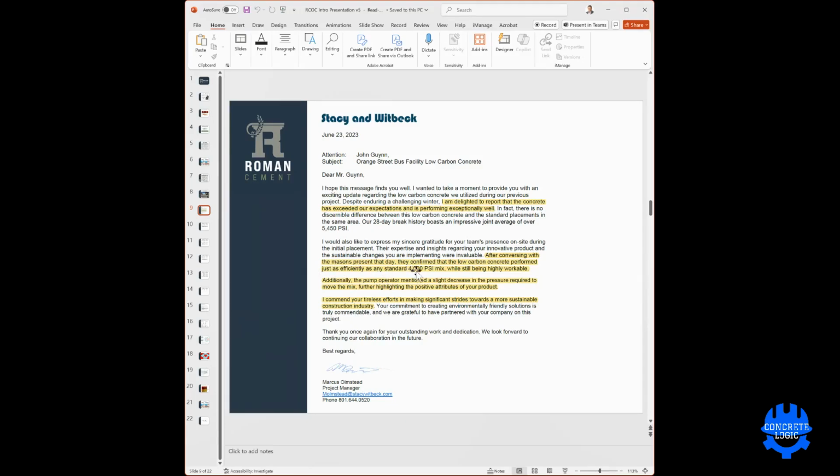And I think that with these new admixtures coming out that are specifically designed for mineral fillers, we can get even better workability than what we got here, because that was not available to us at the time, but it is now. So workability is not something that we have had a problem with, but we do get tremendous strength.